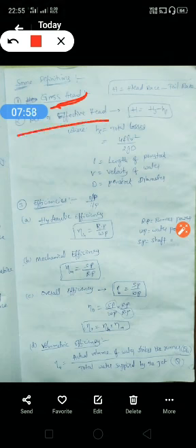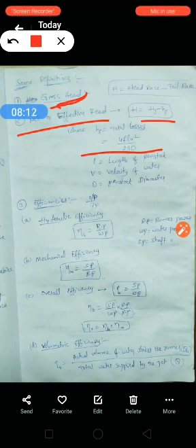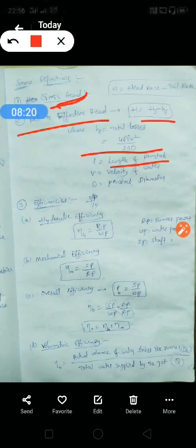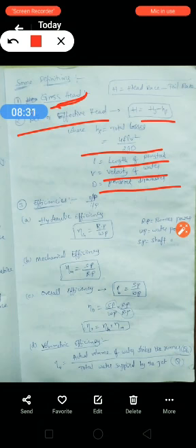And the second thing is net or effective head. So it is the difference between gross head and head loss, H equal to Hg minus Hf, where Hf is equal to total losses, which we know already from the second unit, 4fLV square by 2gd, where L is the length of the penstock, V is the velocity of water and D is the diameter of penstock. So from these values we can calculate the total losses and substitute in the above formula to obtain effective head.